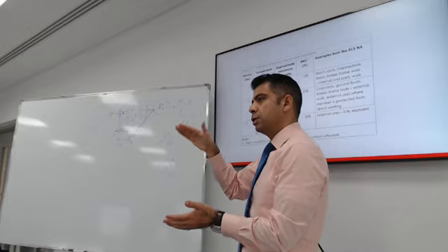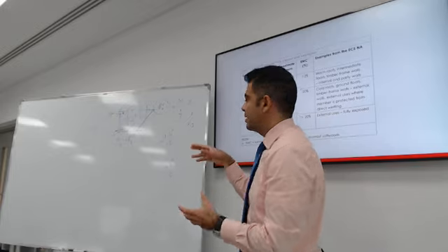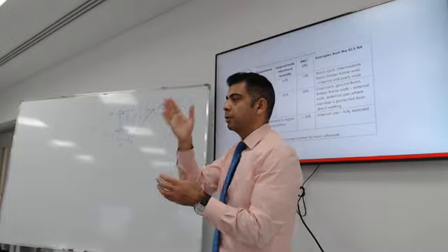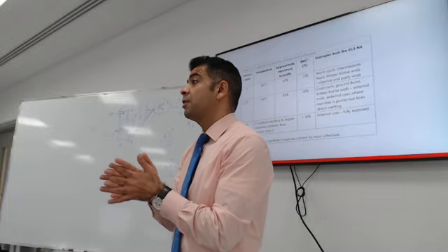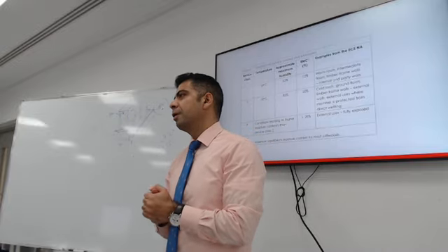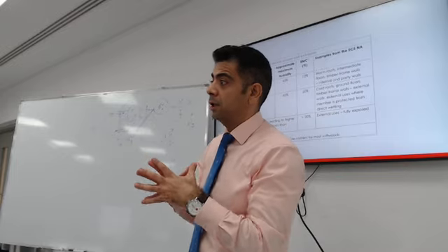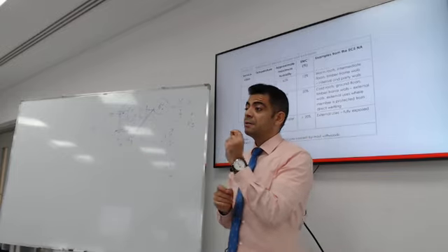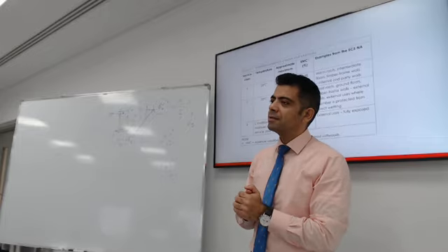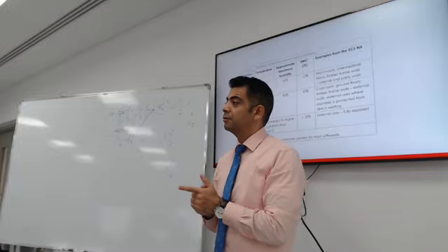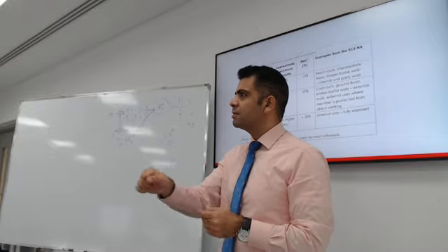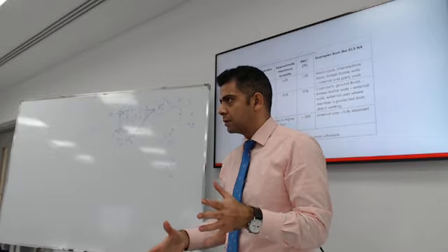And you gradually reduce the exposure of the classes till 1. Class 1 is intermediate floors or internal partition walls. So for internal walls, the difference in temperature is not going to change much. Most of the time we're going to have AC, we're going to have some control of the temperature. It's not going to have very big variations, because wood is very sensitive to big changes of temperature. Can you think of an example of how wood is sensitive to change in temperature? Doors are a good example. When one season the door is working fine, another season it gets stuck, it gets jammed.